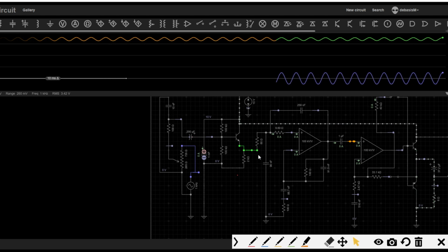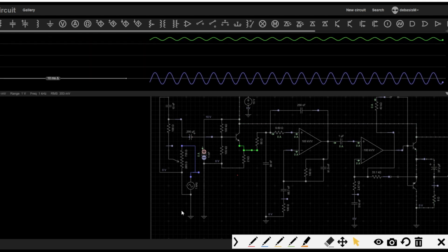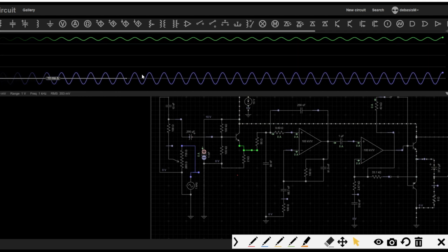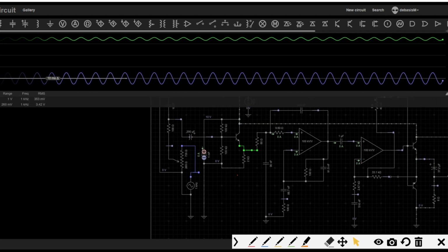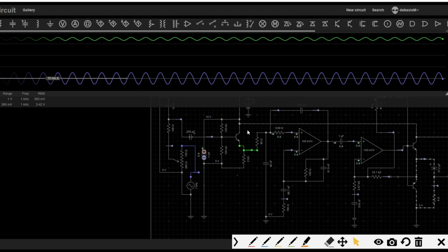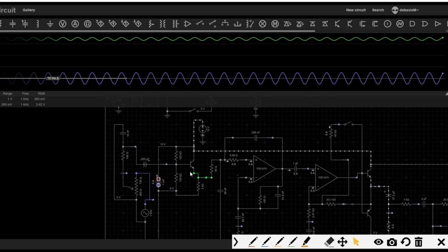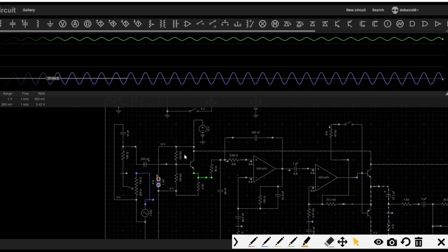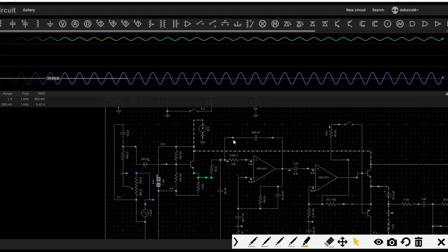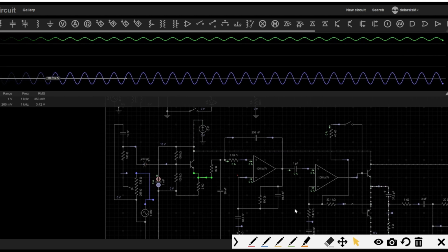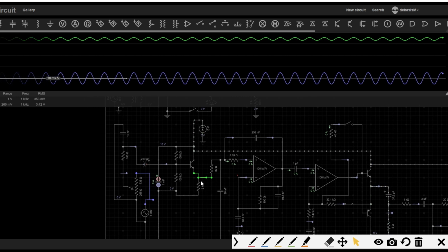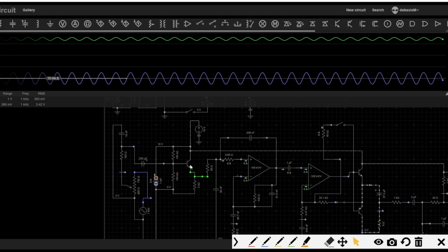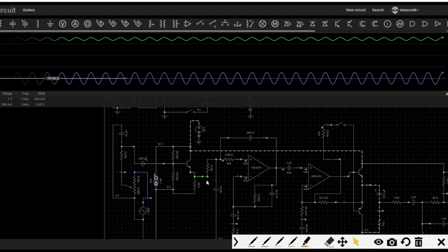So I've just started the simulation. See here, this blue line indicates the audio signal in, which is varying around 0 volt. You can see the range of this voltage is 500 millivolt. What this transistor is doing is clipping this voltage to a higher value, plus it is creating a buffer between this audio signal source and the downstream audio amplifier, filter, etc. The necessary current, whatever is required, is drawn through this route from the actual power supply source.